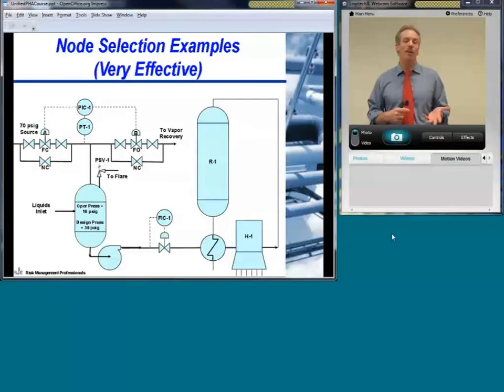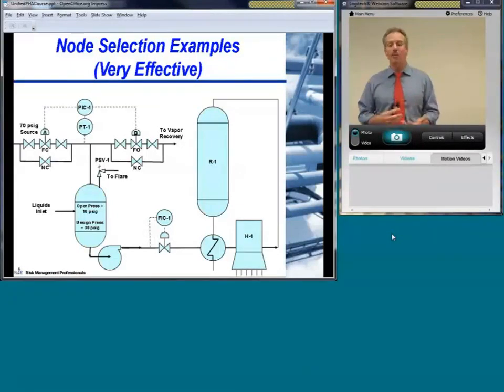You deal with pressure issues in the push-pull system on the feed drum. You're dealing with level issues on the feed drum, the pump and flow control valve, the no-flow issues that also translate into level. And in these typical flow streams, especially at the front end of a hydrotreater, there's not a lot of control required. So there's not a lot of active components between that flow control valve and the reactor effluent.